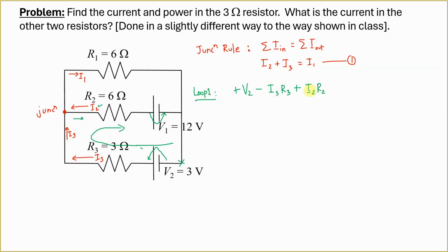So therefore, when moving from the positive terminal to the negative terminal of a battery, I end up with a negative sign. So negative V1, because I'm losing energy as I'm doing it. I'm not doing any real work at this point. So therefore, this is minus V1. So then I end up here. There's no resistance, and I can just go straight down the wire back to X again. There is no resistance. So I've completed my loop.